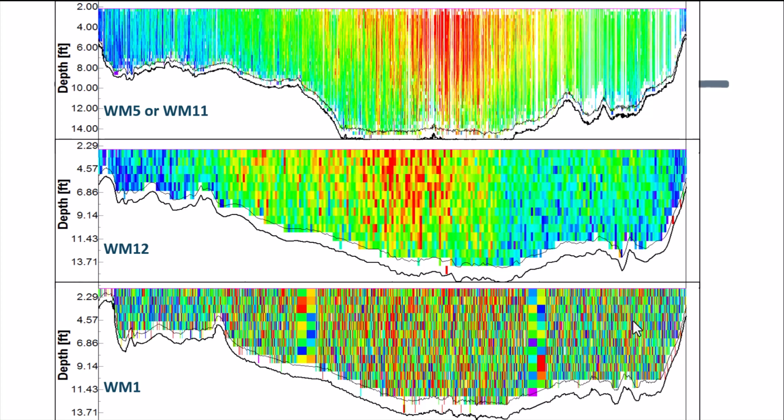The important thing between these three measurement modes at the same cross-section is that the discharges were nearly identical, because there is enough data collected that the random noise was averaged out, and all of these modes resulted in nearly the same discharge.